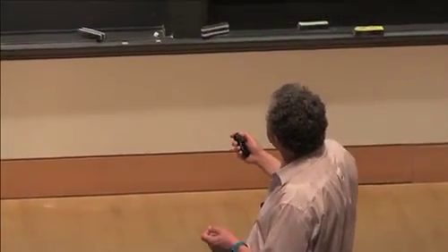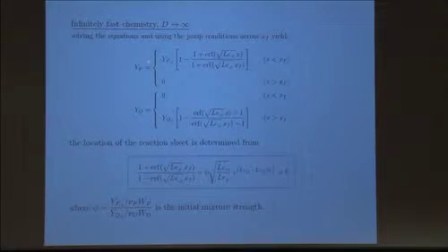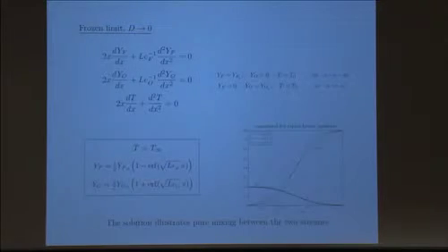The next case I want to show you is the Burke-Schumann limit, D going to infinity. And again, I left the Lewis number general here. The method is, as I showed you before, you solve the equations for the fuel and for the oxidizer. Maybe I should point out that the solution of this differential equation, x d/dx plus the second derivative, is an error function.